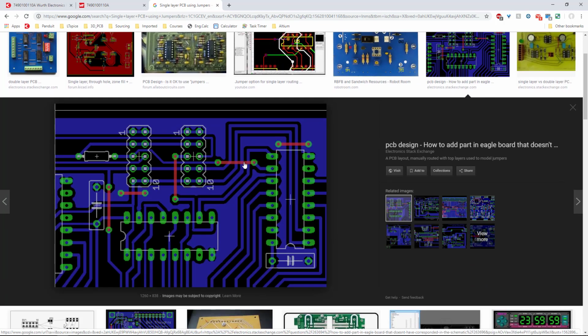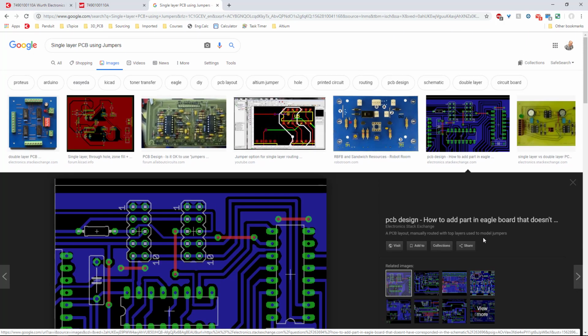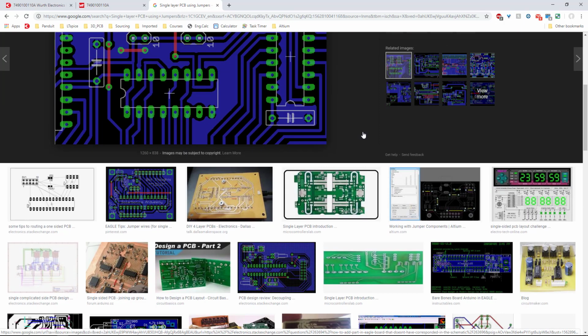Basically, instead of creating another layer on the top, you can put a wire from here to here and solder it on the two sides, and now you are connecting this trace to this trace here. Also, you need to connect the ground in here to the ground in here, and because you have two wires in here, you cannot do this connection, and there is no way to do it from different sides. So basically you put the jumper to connect from here to here. This is very common, an old-fashioned PCB design we used to do all the time when we did single layer PCB.